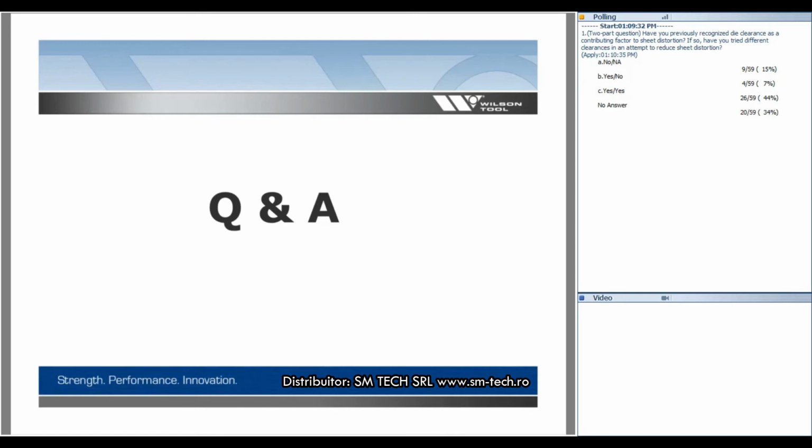Are certain brands of punch presses better at controlling distortion than others? I pointed out the Amada P&F, and that's the only machine that has that particular feature that can hold the sheet with so much force. Now, aside from that, machine manufacturers are creating what they call forming stations. It might be a retractable die system, they'll call it.